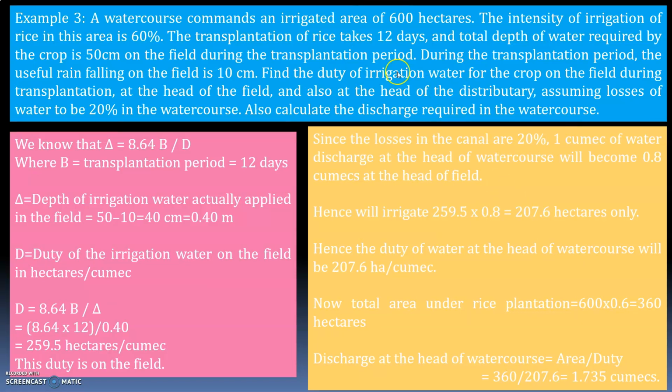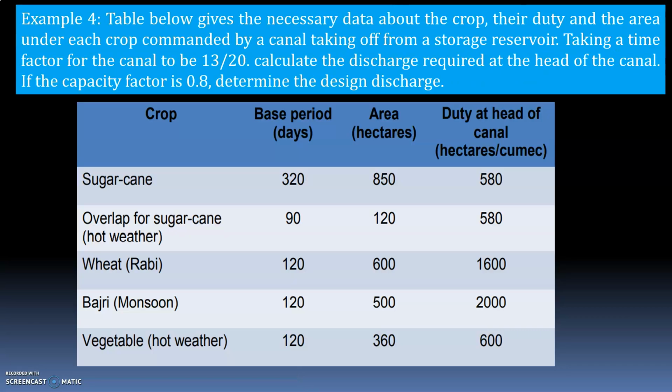So like this, you have to calculate the duty of the water on the field during transplantation, and the duty at the head of the field, and also the discharge in the water course. I hope all of you understood. We'll take one more example.